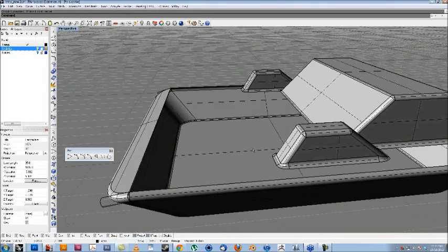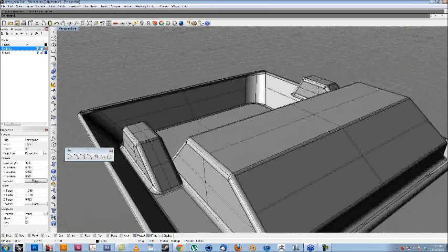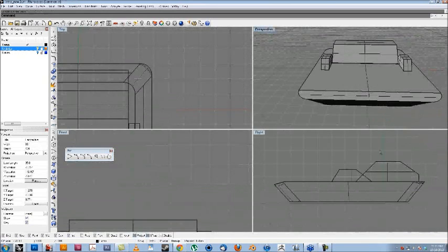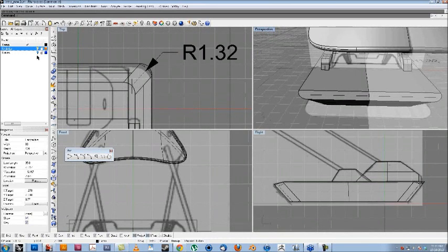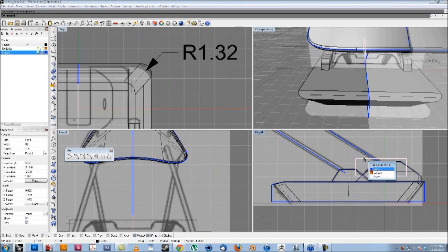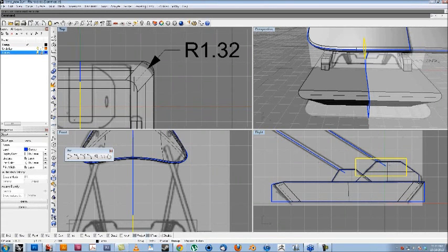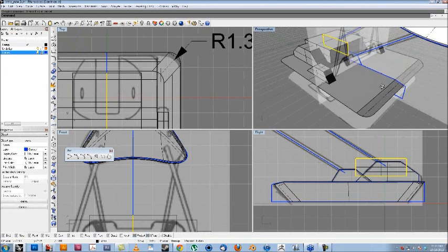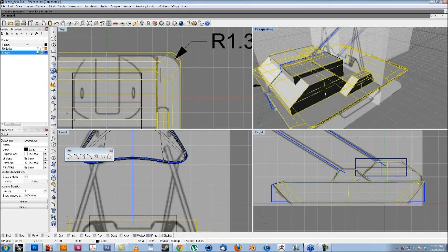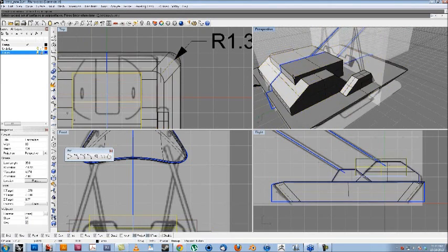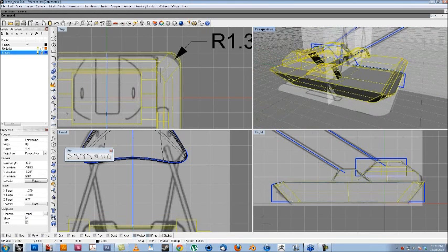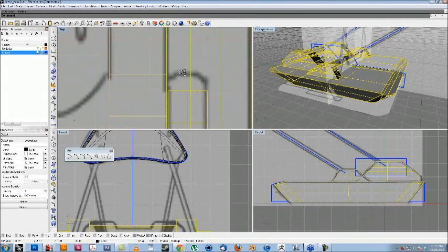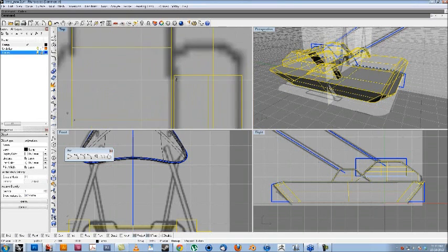Sometimes if your fillet's too big, you'll get a lot of crossing faces, such as right there. So what I might do is actually, oh, you know what? We forgot one quick little thing here, and that is we need to extrude out this little guy too. And then Boolean that out. So we'll take that. All right, that's a little closer to what I had. And the other thing is we've got too close of a gap here for the fillets to work.